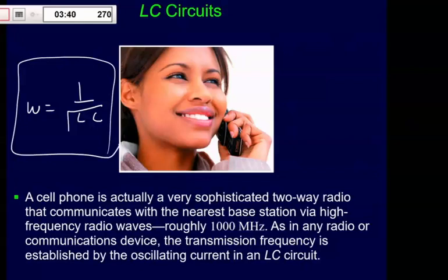And so if you're building something like a cell phone that you want to only accept certain kinds of frequencies and basically block all the other noise out, one way to do it is to have an LC circuit, because it's a really finely tuned circuit that only allows, or at least strongly prefers, oscillations right around that angular frequency. Questions on that? That's definitely the one thing, for sure, I would say, you want to remember about this stuff. Okay, I'll be down here if you got questions.